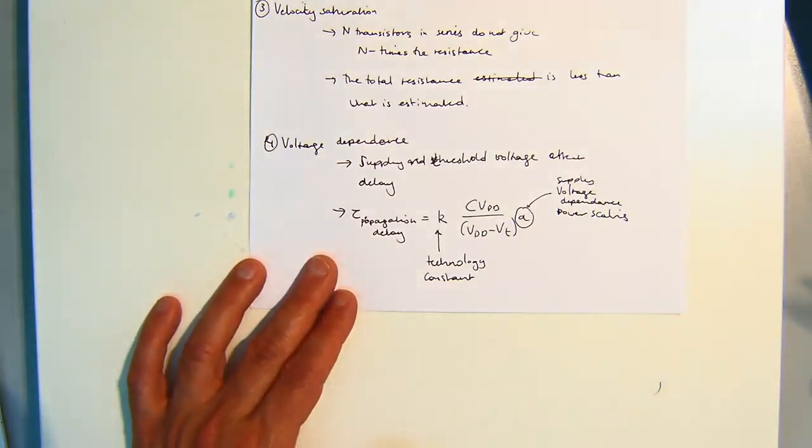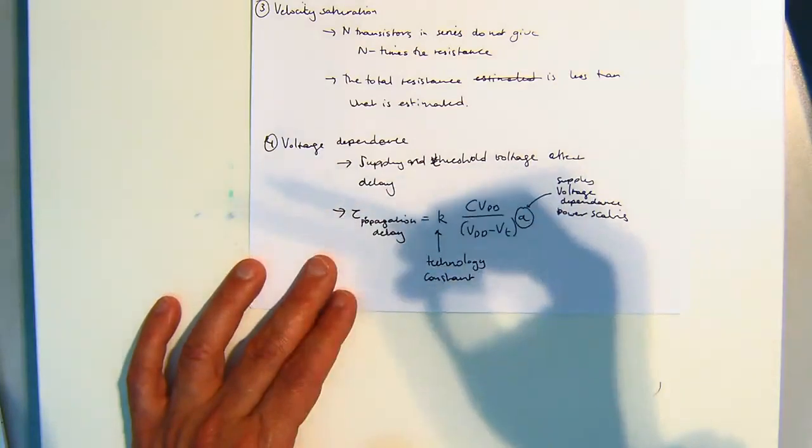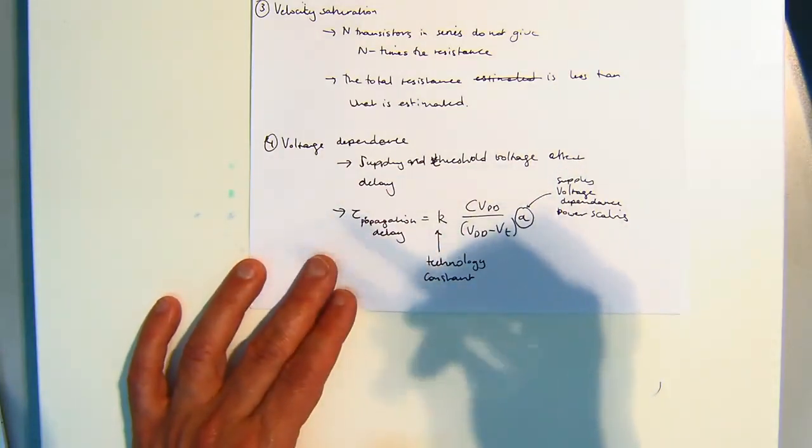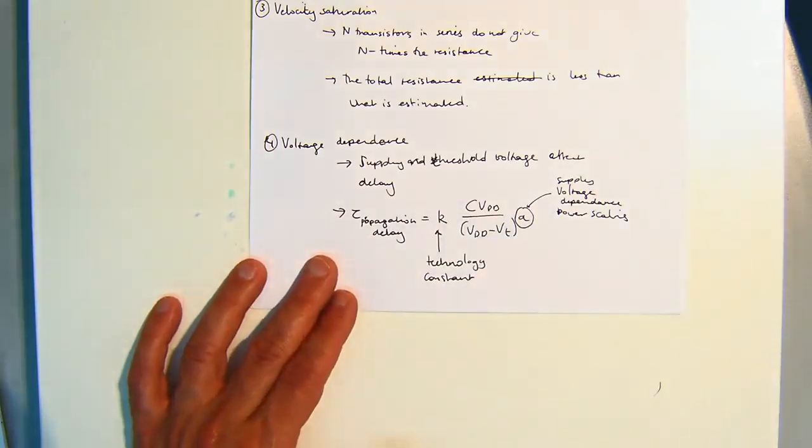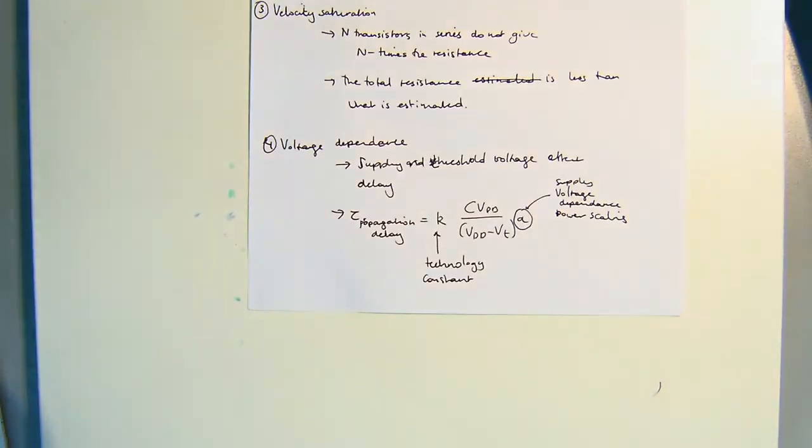Now, why did we decrease the voltage? We said we could decrease the voltage, and why did we want to maybe decrease the voltage in our logic? To lower power consumption. And why voltage, not frequency? That's right. It was V squared. Remember, it was half C f V squared. Perfect. All right. Excellent.